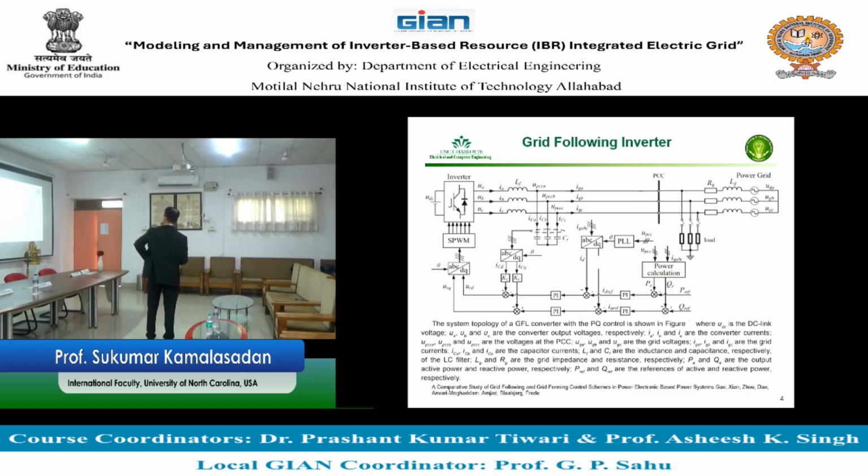So having said that, the inverter has electronic switches inside, and those switches are controlled by PWM, pulse width modulation, or sine PWM, sine pulse width modulation. And there are 6 such switches, 3 on the positive side and 3 on the negative side. So those 6 switches you are controlling utilizing 6 pulses that go to the inverter, and these 6 switch pulses are derived from 3 voltage signals.